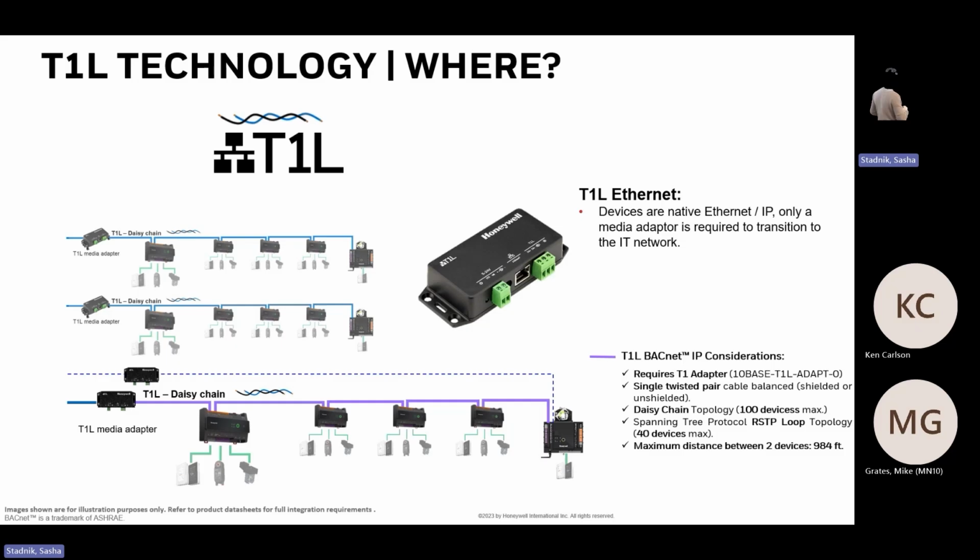Completely. So in retrofit applications, for example, let's say the end user says, I don't have the money to do this. Even if I change the controllers only and keep the wiring, I cannot invest in all those controllers in one single shift. So what can you do? Let's say you have this one as an IP. Just imagine they are IP, Cat5, Cat6. And this one was Cat5, Cat6, but the end user is saying, I can invest in 3 on this branch. What am I going to do?